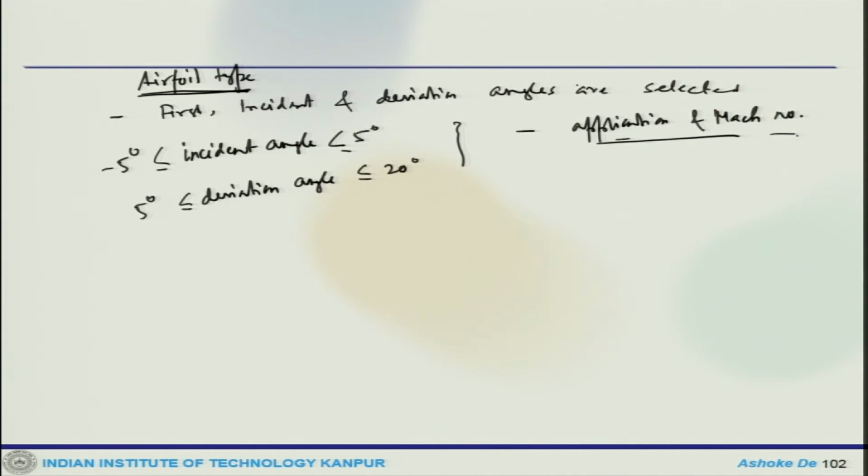So, these things we have already looked at, and the typical series which is used is the NACA 65 series blades. These are typically used. Then there is another series, this is American, and then there is a British series called the C series. So, these are also used in the compressor.